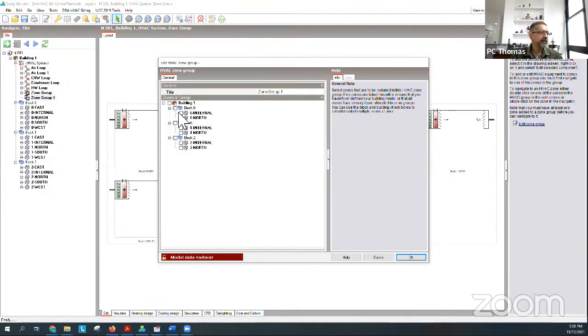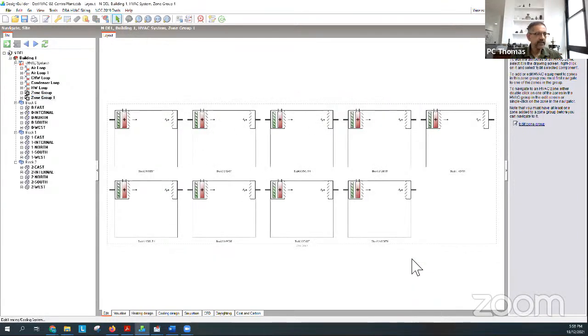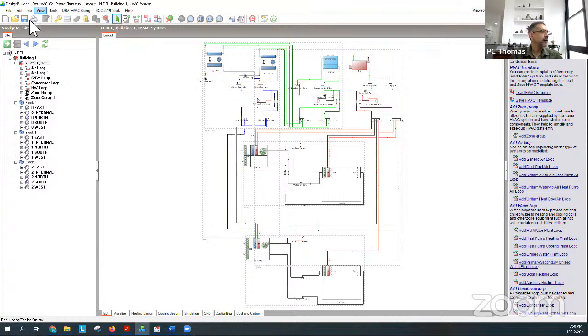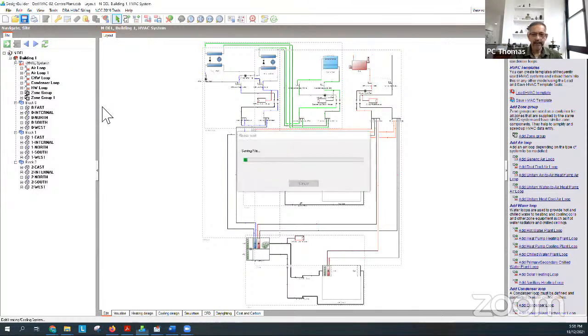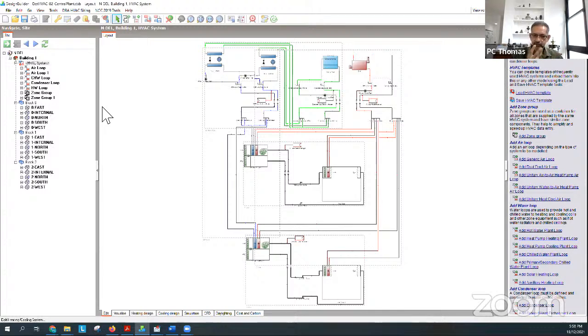And the ones that I released, I'm going to add over here. So zone group 1 is all the center zone type zones. Okay. And now I'm ready to run this model. When I run it and look in detail, I should get 2 chillers running, and I should have 2 air handlers running, doing different zones.